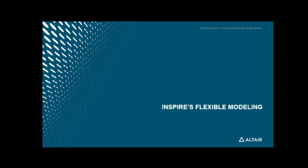So what makes Inspire's geometry modeling so flexible? Well, I think I can break it down into about 5 key goals for Inspire's modeling capabilities. The first area is that all models in Inspire can be fully parametric with end-to-end editable history. So either if you're starting with a dimension sketch or importing some external geometry, every single modeling operation that you do inside of Inspire is captured in a single continuous history with key design variables that can be extracted for either editing or for optimization.